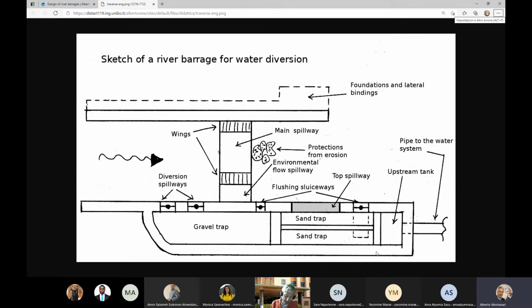Remember what we discussed in terms of design of the sand trap, not the Stokes formula, but design of the sand trap, and what we said about the minimum submergence and why I should make sure that I have a submergence. This is something that I may ask at the exam. A question may be, why do we need to ensure that a minimum submergence is kept over the top of a pipe flow that is bringing water downstream?